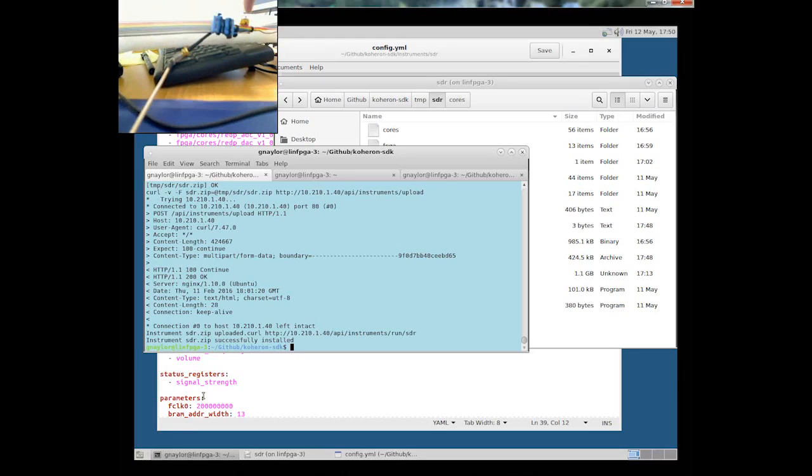and so the extreme ends of the ribbon are taken out to this SMA connector here. In parallel with the loop we have a trimmer and some polystyrene capacitors, and that comes to a few hundred picofarads. So with the 60 picofarads of adjustability here, we can tune to whatever receiving frequency we want. We're going to try and pick up Radio 5, which is at 909 kHz, and so we can pick that up in the AM band.